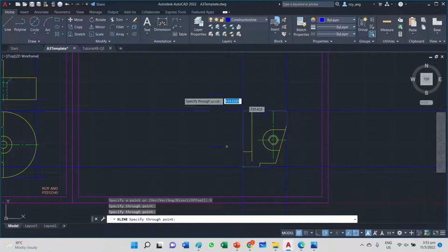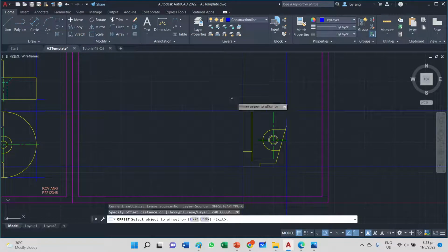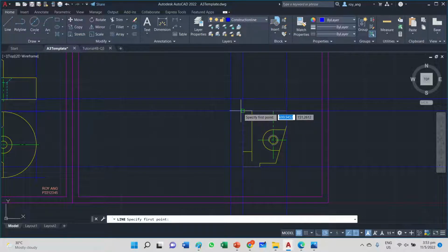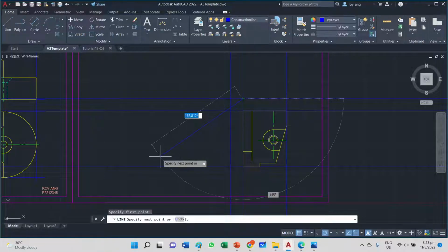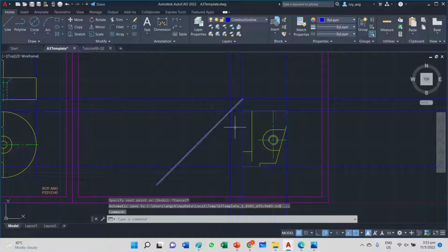Horizontal. And after we draw this rectangle, what's next is I'm going to draw a part of this hexagonal line on the slope, the 45-degree line. And how I will approach this is that I know, let's put it all the way to 200, that it goes from here up. But the end point, I do not know where the end point is for this.